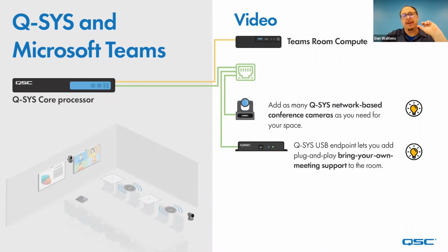Also, don't confuse that. Sorry, I was answering some questions, so you may have already said this. The IO USB bridge has a 2.0 port, but you still get full motion video. So I'd like to reiterate that. It seems like no matter how much we say it, people ask that. And I want to say it took me a few months to get it. Even working with the product regularly, it still took me thinking, no, it's just the Core 110. It's not a software limitation. It's the hardware of the Core 110. That's the limitation. So we try to make that noted. If you're using that as a bridging port, try and keep it 3.0 if at all possible.